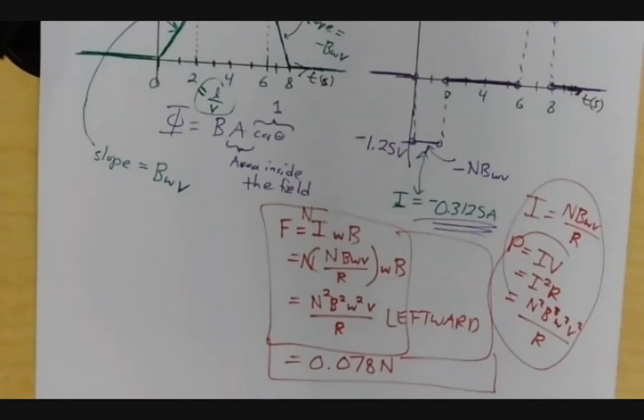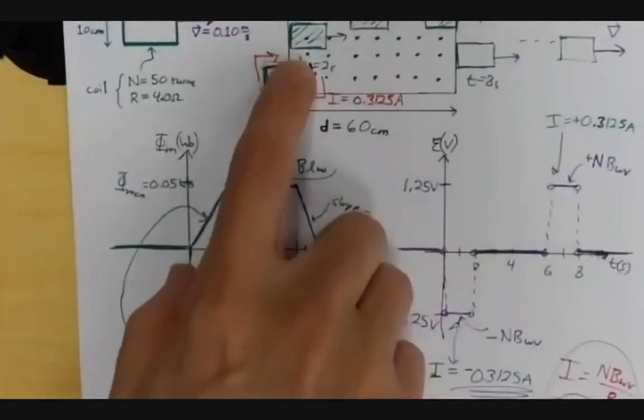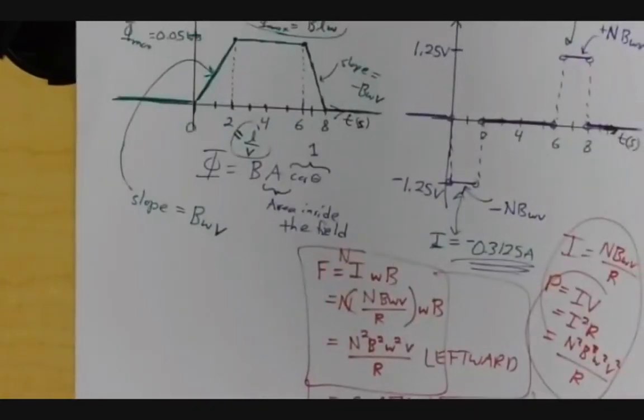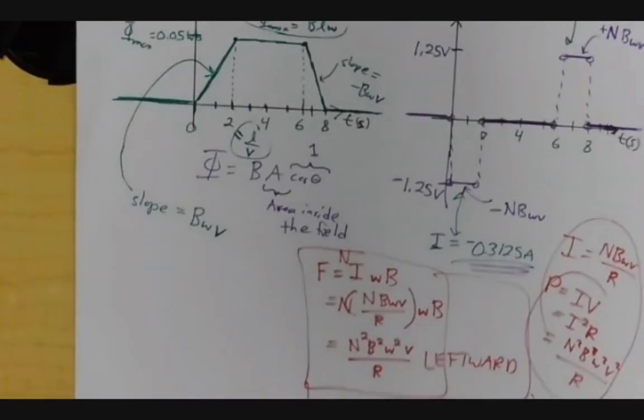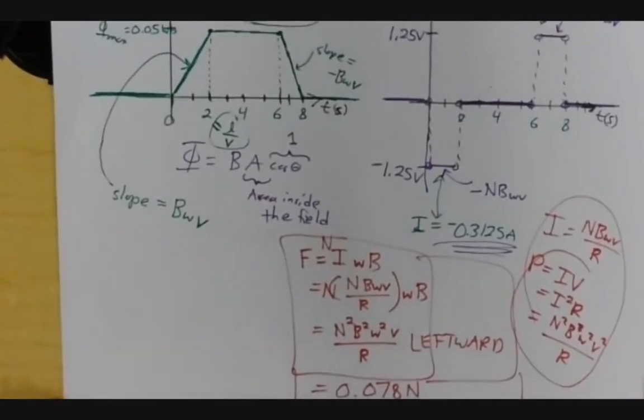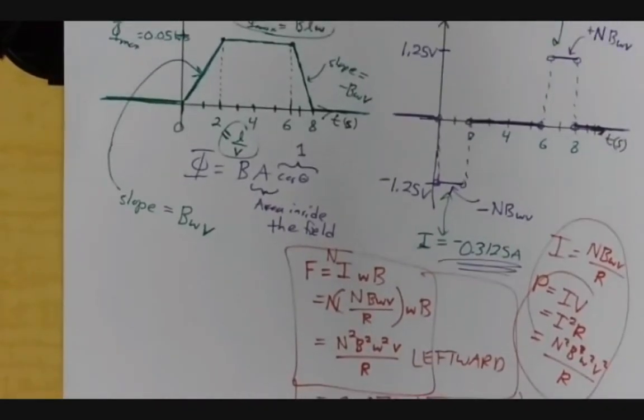It's I squared, one factor of R. If you do this with a piece of wood, what's going to happen? It's going to have such a high resistance that nothing's going to happen. Okay, so power, we can make it work. Just take this and multiply by L over V, and it would become the work while entering, because you're going to apply this power for what interval of time? The entering time is the length of the loop divided by the velocity at which the loop is moving.